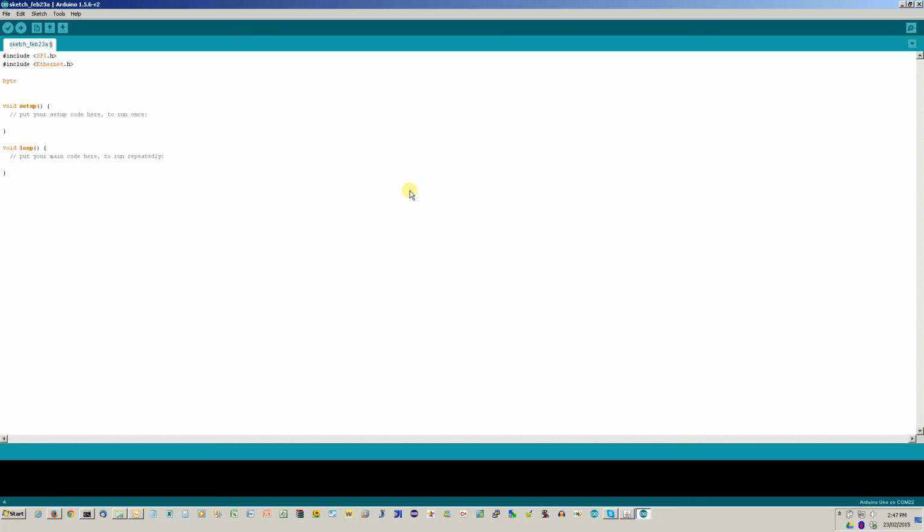The first thing we do is to add a set of variables that will be used in the code. We need to set a MAC address. It is important to pick a value that you do not have in your network already. Newer Ethernet shields come with a hard-coded value, but for the board I used I have to provide a MAC address from the code.